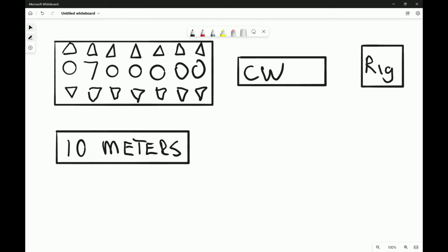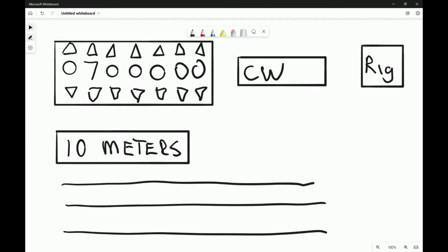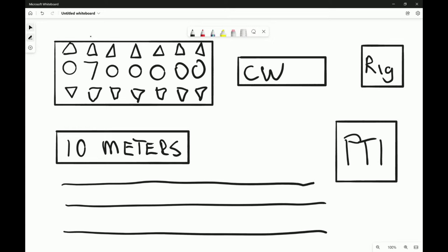They'll tie into the frequency control so that when I select a certain band, it resets the frequency to the start of that band. The other thing I think I'll have, tied into the band, will be just some text description of what you can do in that band, again because I'm a new ham radio operator. That'll be useful. And finally, I'll need some way of changing from transmit to receive. So it's normally done with a PTT control, so pressing that will switch the transceiver from receive to transmit and back again.